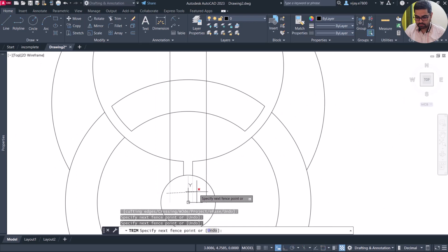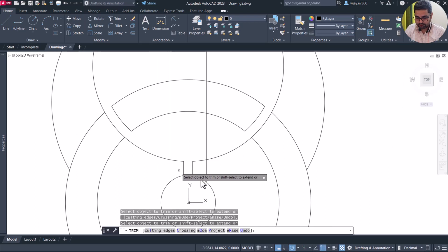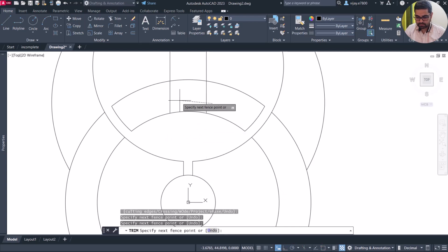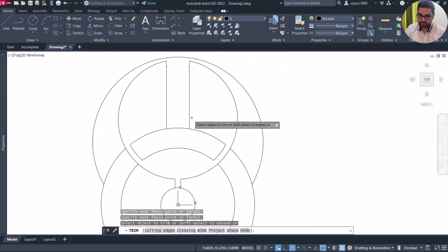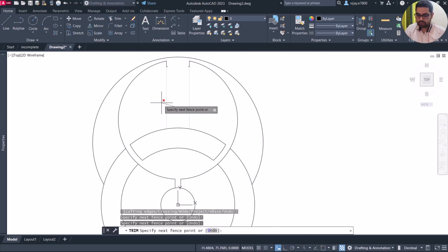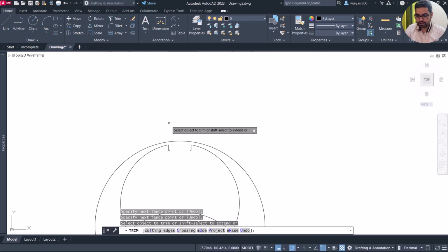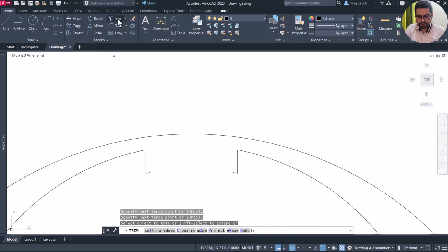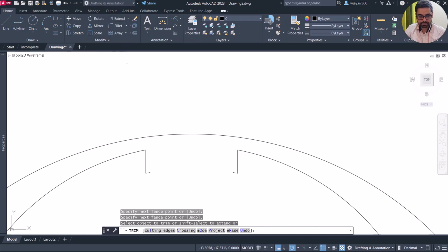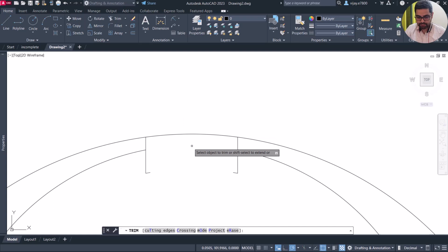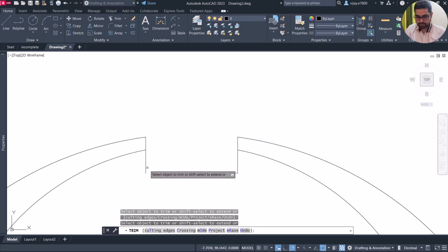Now, once we are done with removing all of these things, you will see that the drawing looks a lot like the required drawing. And now we will simply create an offset. But before that, we are going to extend these commands. So click on trim these lines, click on extend. Now extend this line, extend this line. Now use trim again, remove this excess portion that are not a requirement anymore, and click OK.